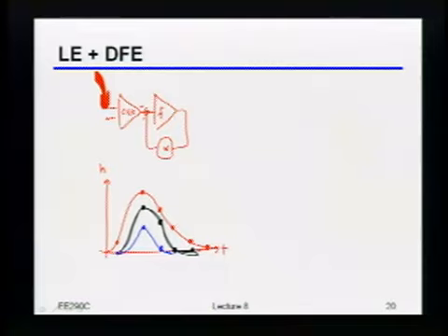And so if you try to do everything with a linear equalizer, you'll amplify that crosstalk. So even just from that standpoint, oftentimes you'd want to do the DFE so that your continuous time linear equalizer won't be peaking the crosstalk. That really has nothing to do with thermal noise, but for the same reason that it peaks thermal noise, it also would peak crosstalk. Okay? Does that make sense to people?